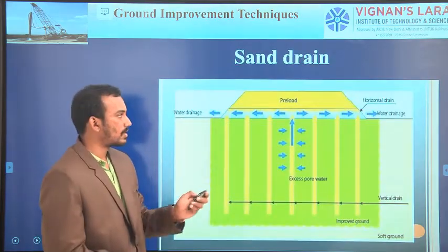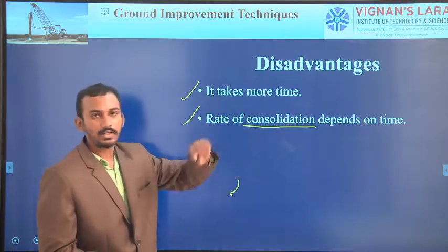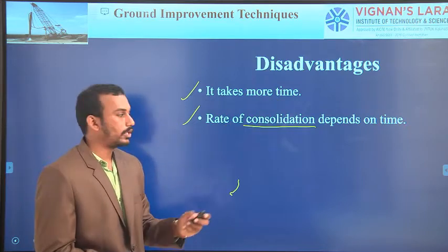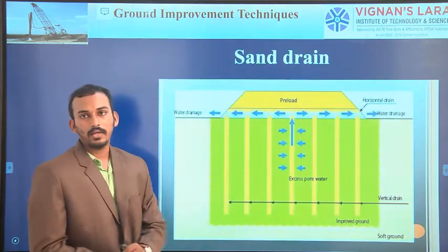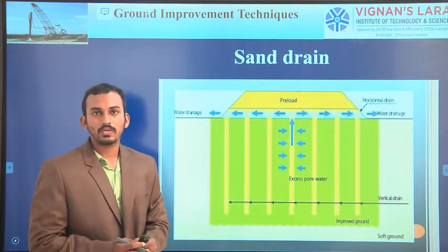Okay, what are the disadvantages? It takes more time. Rate of consolidation depends on time. These two are related to time consuming only. So to reduce the time, we develop a sand drain method. It is very similar to the preloading. So what are we implementing?